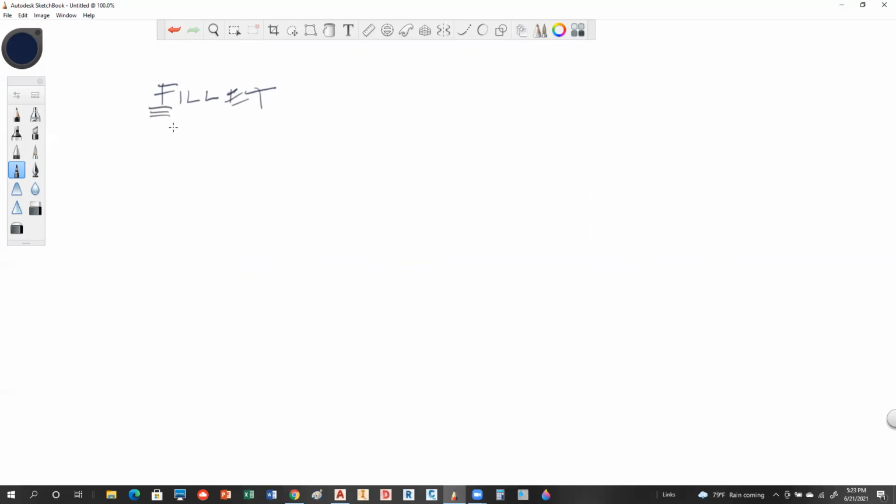So you want to know that. So a fillet will do one of 3 things. It'll generate a true fillet for you, which I'll explain what that is here in a minute, or it will extend, or it will trim, depending on what you do this for, or how you have it set.